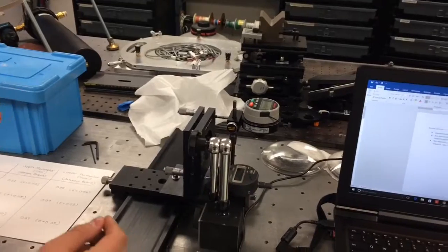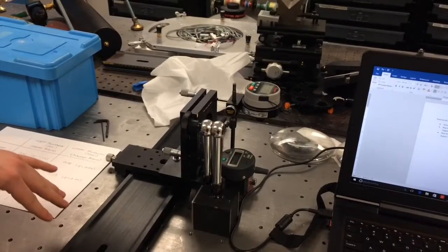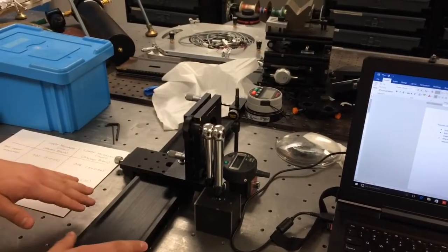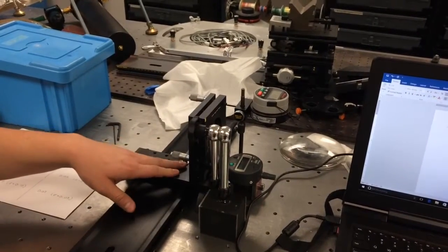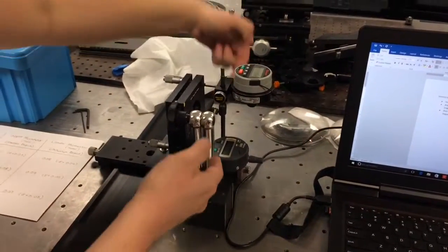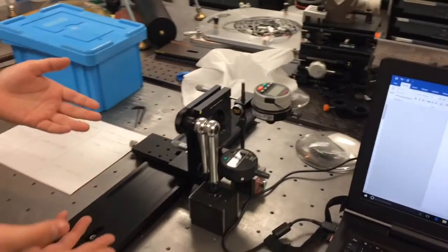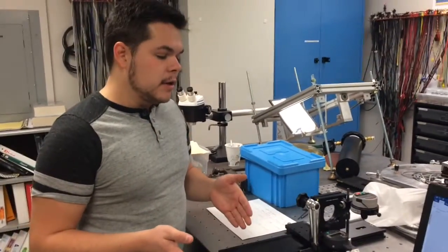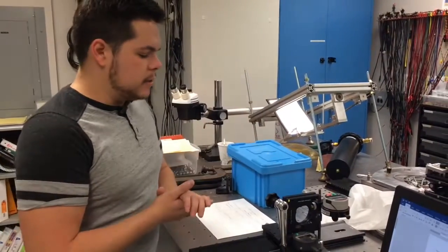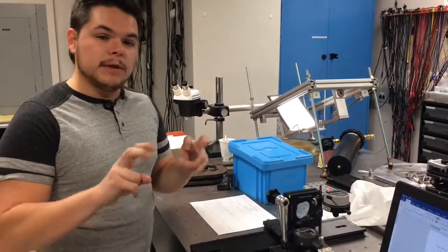So there's a lot of other reasons. There's so many moving parts that came with our setup. We were careful not to touch the table while we were making measurements, so the vibration in the table probably was not a factor, but the rail could have been moving a tiny amount, the stage, the mount itself could have been shifted on the stage. We have magnetic bases that could have been shifting slightly, along with arms that were connected with joints, and those connected to the indicators themselves. And these indicators are so sensitive that all of these moving parts could even be changed with air current. I can see them changing right now and I'm not even touching them. So those were other potential sources of error that might have affected the repeatability of this experiment.